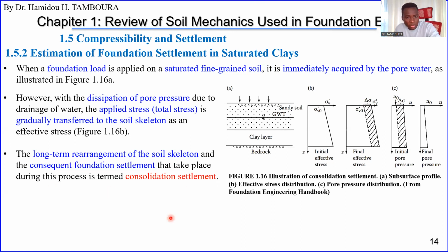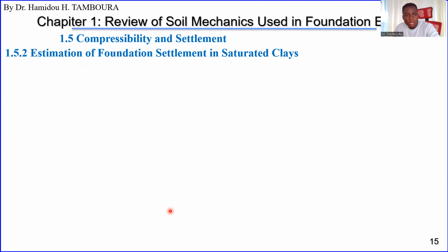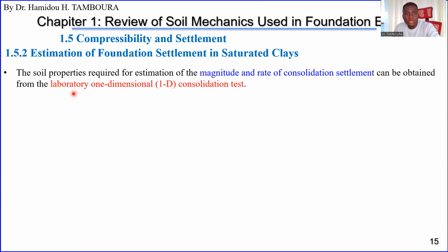Consolidation settlement. So this consolidation settlement can be measured in the lab. The magnitude and rate of consolidation settlement can be obtained. We call this the laboratory one-dimensional (1D) consolidation test.